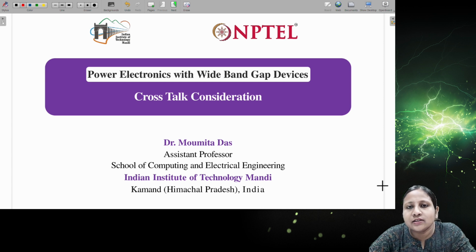In the last class, I started discussion about the crosstalk related considerations. So how the problem during the turn on and turn off time of the switch is happening and how we can mitigate them. In the last lecture, I discussed mostly about the passive type of consideration, so what kind of solution exists if we use the passive components, and also I started discussion about the active related solutions. As you have seen in the passive solutions, we can either connect capacitance or we can supply negative voltage.